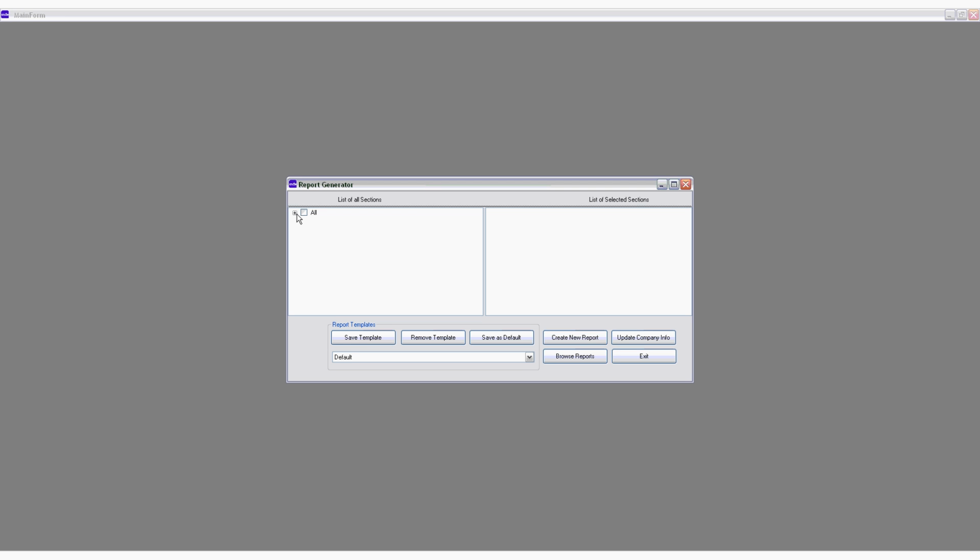If we expand this function, we can see that there are options such as Report Cover, Table of Contents, Structure, which can be expanded to include other options, Construction and Solution Data. This can be expanded to include any stage solution, non-time-dependent solutions including the base load, post-tensioning, long-term, and the current combination, friction and elongation, and also torsion. Any number of these reports can be selected to create a customized report.